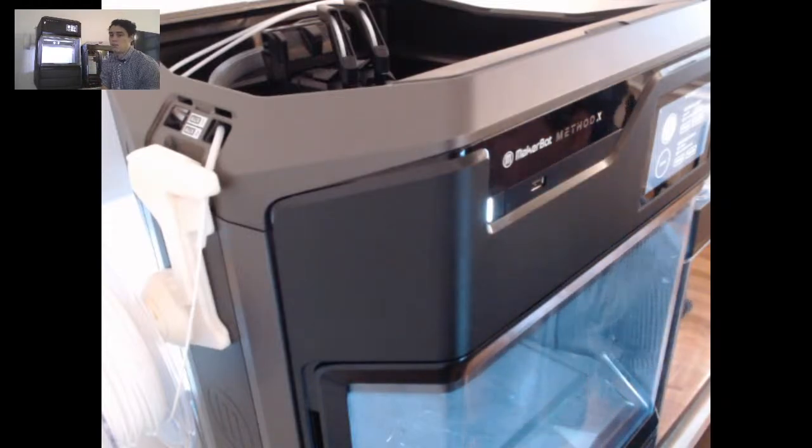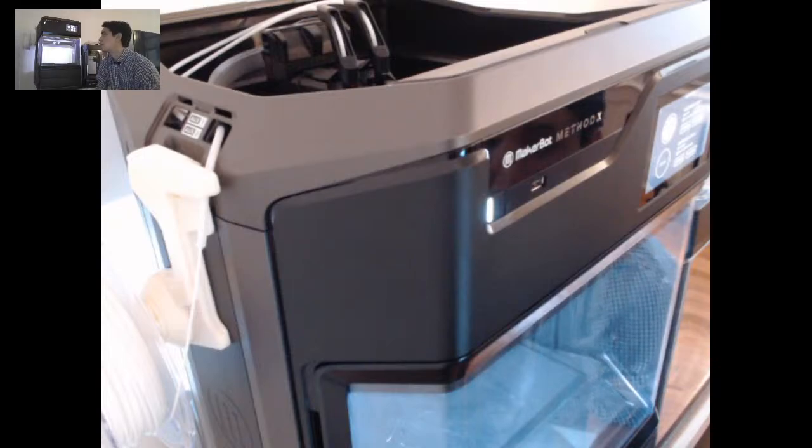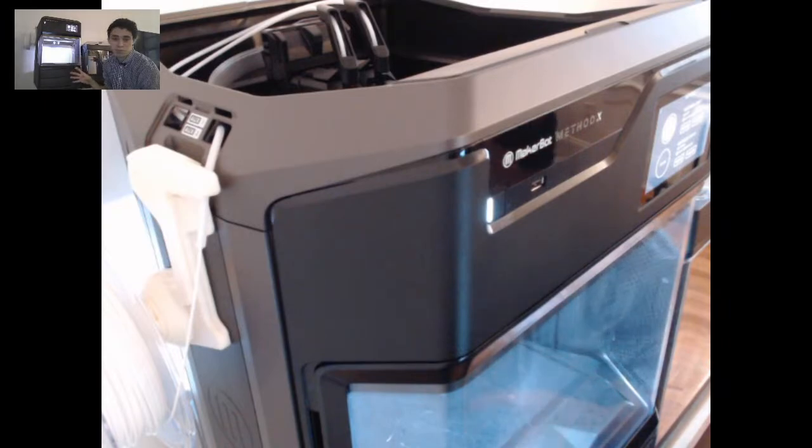That's not often. I haven't had to do it before in the method. It actually takes a long time for you to damage those nozzles. They are stainless steel nozzles, so they will last quite a long time. If you have to do it, maybe every 6 months, but if you get a clog, or if you're using any sort of weird material that just collects itself in the nozzle, then maybe. But yeah, how can I tell if a nozzle is clogged?